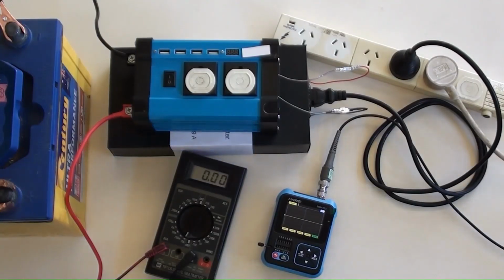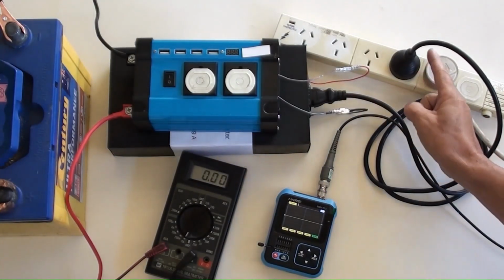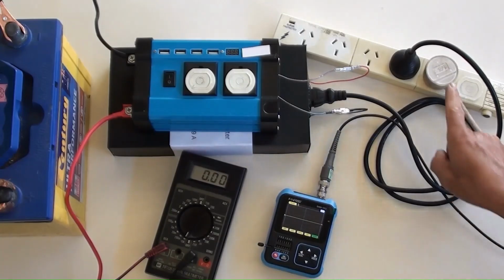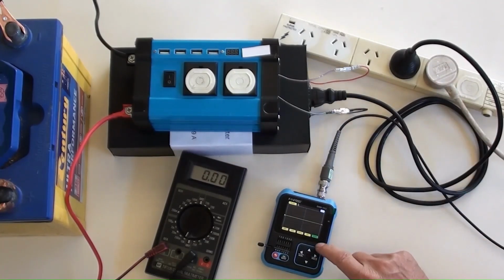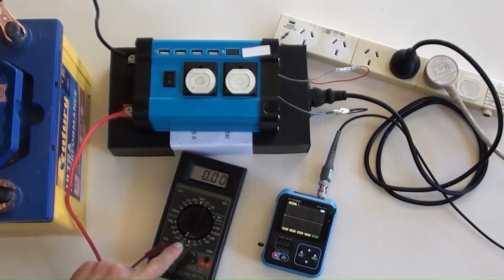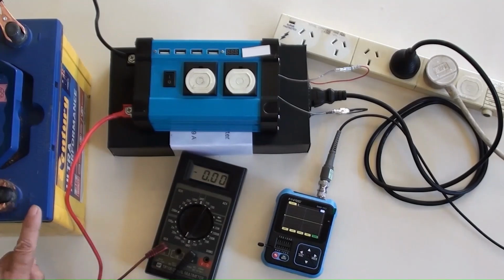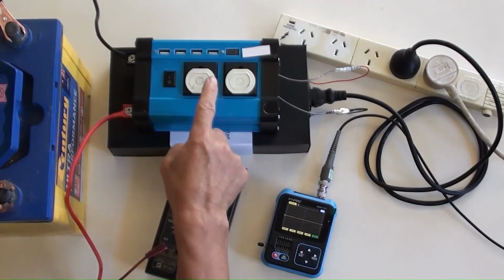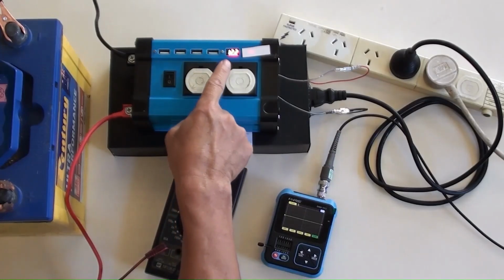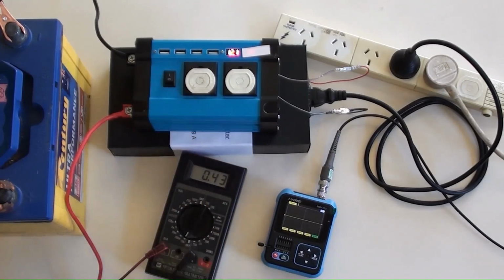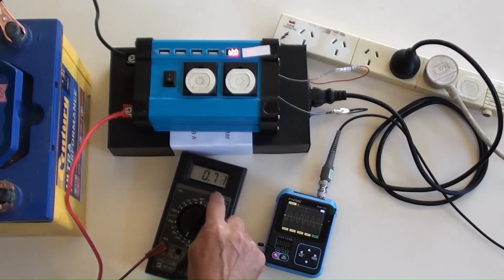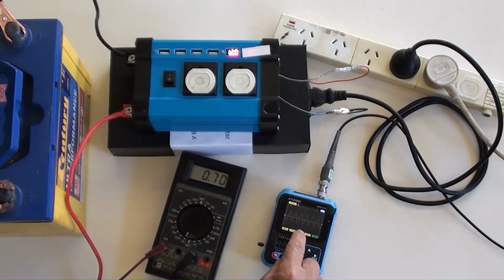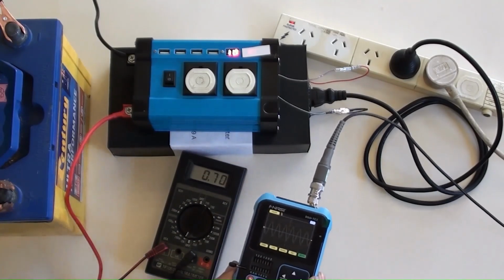Things have been set up for testing run. The black cable plugged into the multi-socket set from the inverter's output, the white cable connected to an oscilloscope, and the multimeter's ampere position selected for no load measuring from battery. Connected battery. Then turned the switch on, the multimeter indicated 0.7 ampere for no load current from battery to the inverter, and sine wave indicated on the oscilloscope.